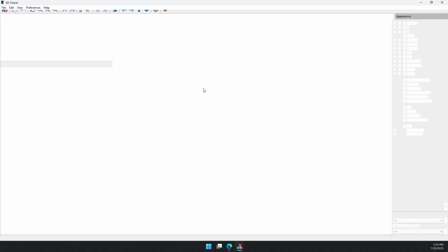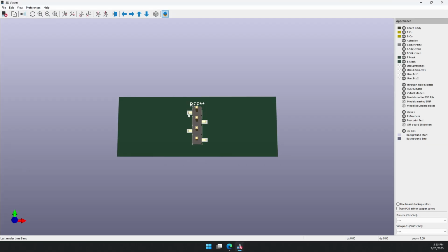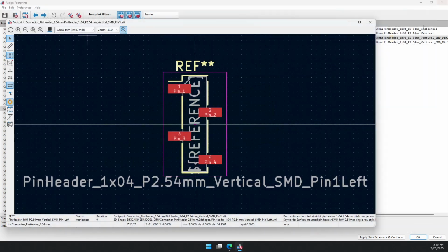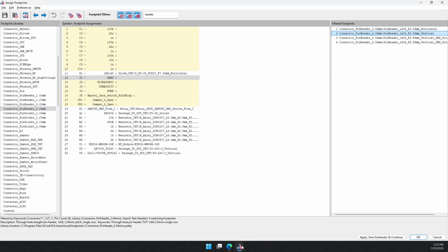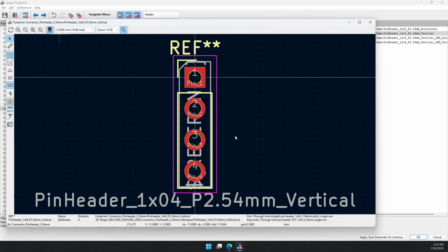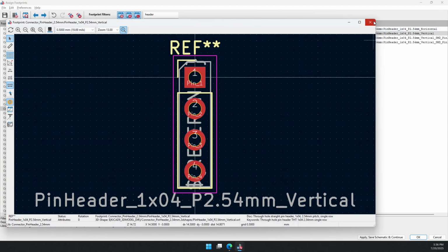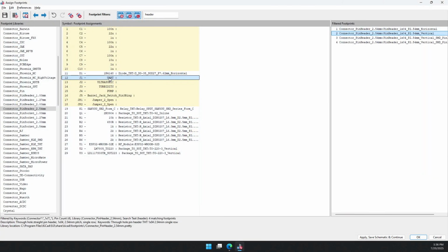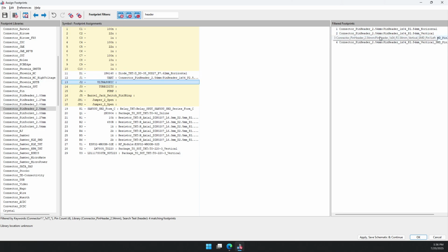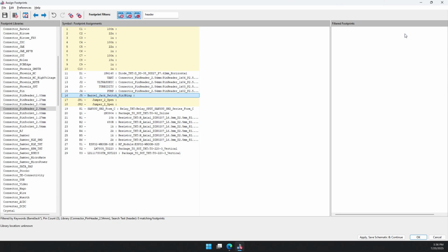You look at it, it's soldered on top, not soldered through. The one we want to use is this. It's soldered through the board. Okay, so it has already filtered it. For the UART, it's a 4-pin connector, right? So we select this. Ultrasonic tool is a 4-pin connector. Select. Stability is a 3-pin connector. It has changed. So select. Pump is 2-pin and it has changed. So select.